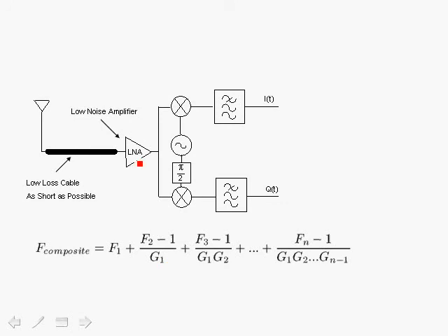This is one reason why LNAs are external components, so they can be built from devices that have a low noise figure and a high gain. Recently, manufacturers have been able to build on-chip LNAs and achieve very good performance. We have shown some of those devices and introduced some of those vendors in this presentation. But that is the challenge. In order to improve sensitivity, sometimes you have to use external components, external LNAs.